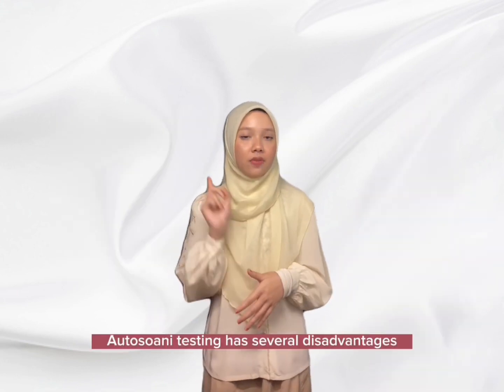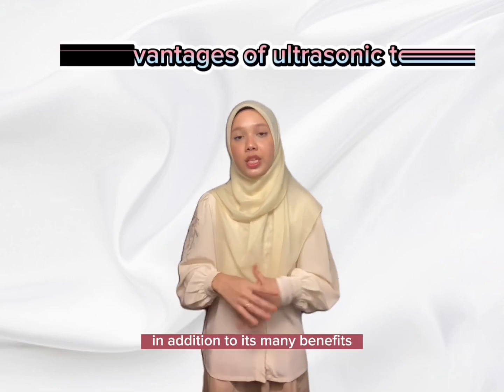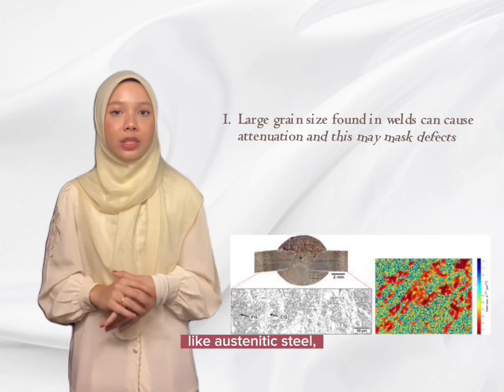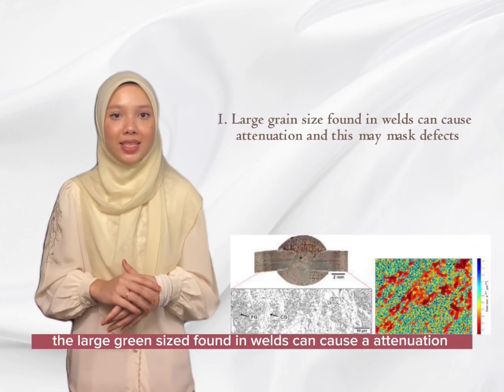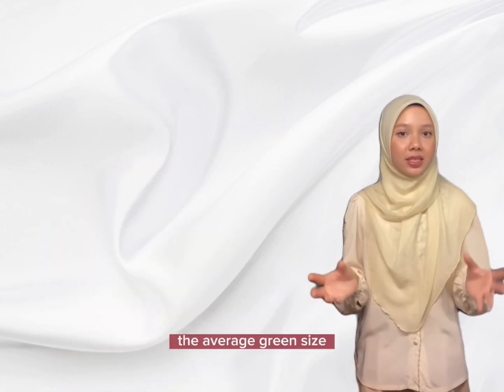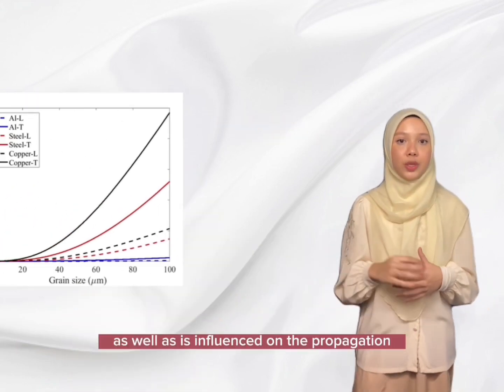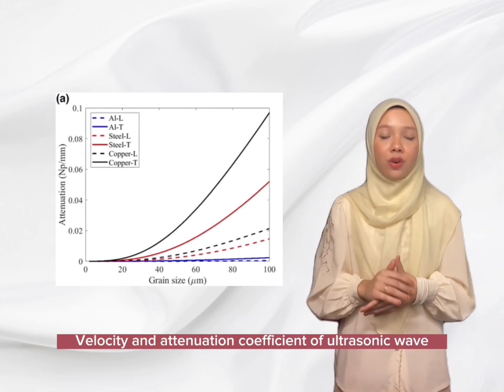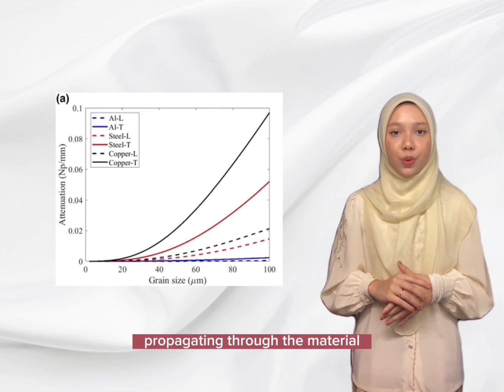Ultrasonic testing has several disadvantages in addition to its many benefits. First, in certain materials like austenitic steel, the large grain size found in welds can cause attenuation, which may mask defects. The average grain size as well as its influence on the propagation velocity and attenuation coefficient of ultrasonic waves also affect the wave frequency propagating through the material.